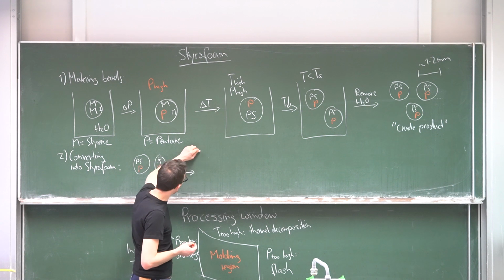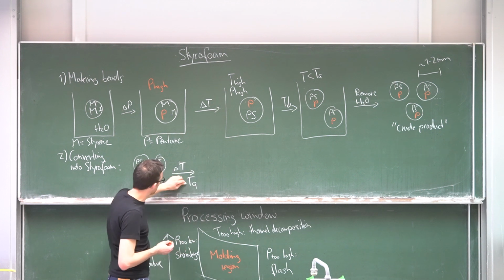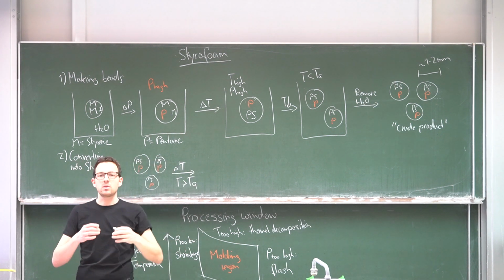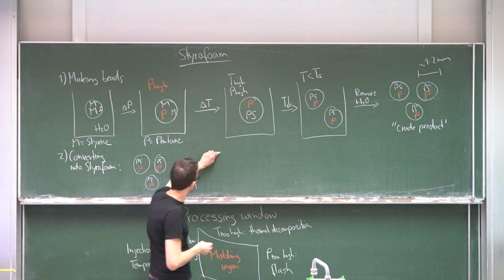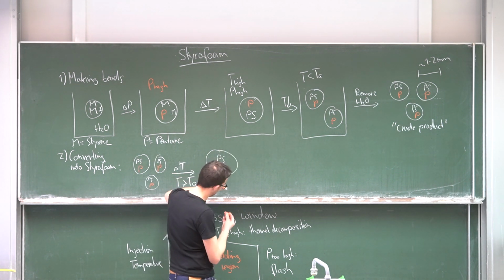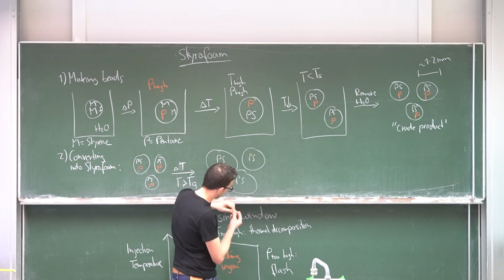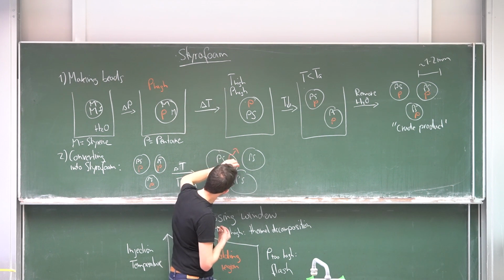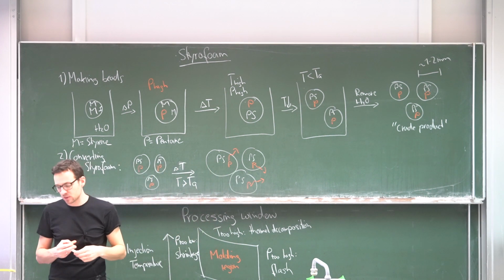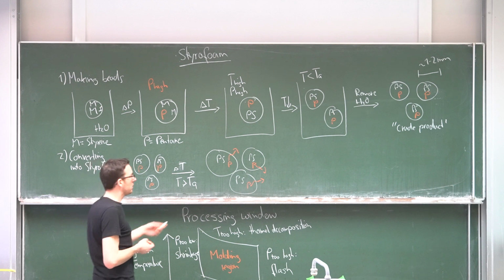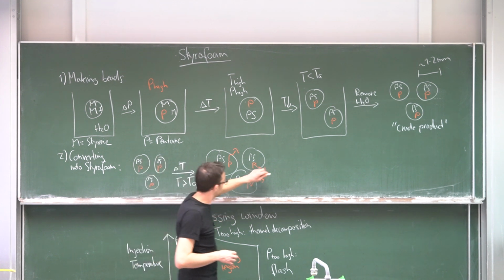That means that now we go above the glass transition temperature, and that means the polymer becomes soft, the pentane can escape, and by this foam up the polymer. And the pentane, at least partially, escapes. So now we have our puffed up polymer particles with maybe a little bit of pentane remaining, or also not,